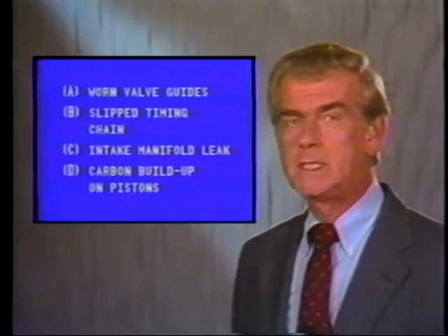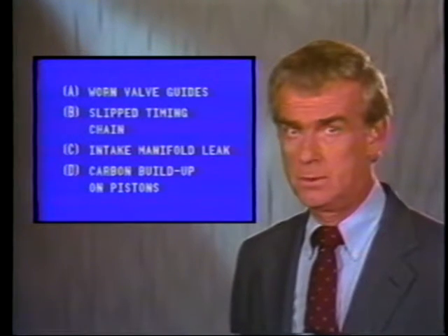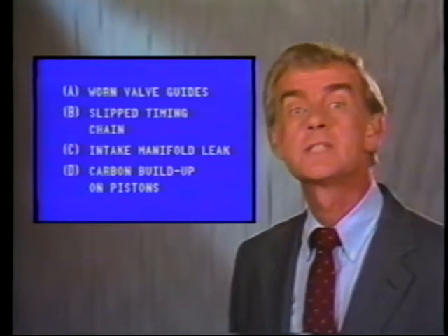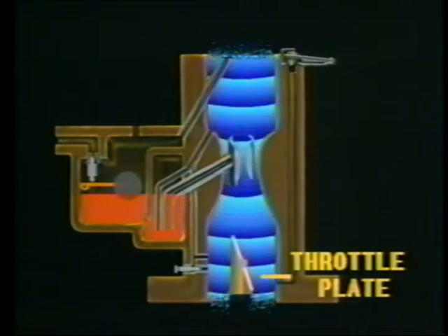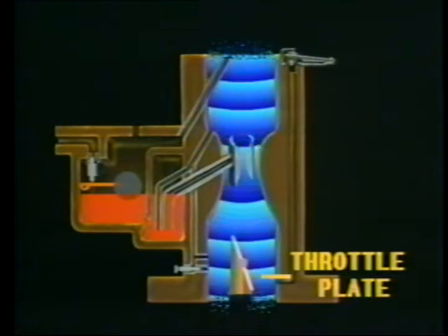Looking at the possibilities, we know that an intake manifold leak would have no bearing on a compression test for several reasons. The most notable being the throttle plates should be blocked open during the test, allowing as much air as possible to fill the cylinder. An intake manifold leak would not alter the air entering the engine in this case.